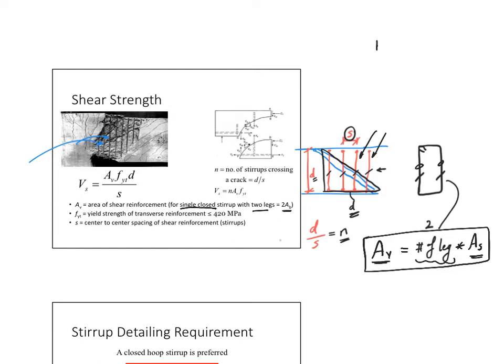If I have a section that has more than this, for example, such big sections happen a lot with bridge caps, those big bridge elements, you would see a stirrup that looks like this. There are a lot of bars that come inside this, right? And then imagine that I will have more stirrups inside. So I have another stirrup here, and then another stirrup here.